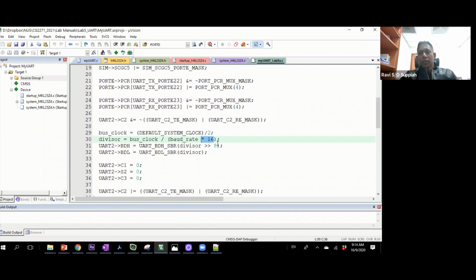Okay, what if there is a tie? If there's a tie, it may interpret either way. So it may flag an error if you have enabled parity checking or something like that. Or in the event there is a tie, it may set one of its own error bits. In the UART module, there are a few error bits there. So it may trigger one of those error bits to tell you that there is an error in the data due to noise.